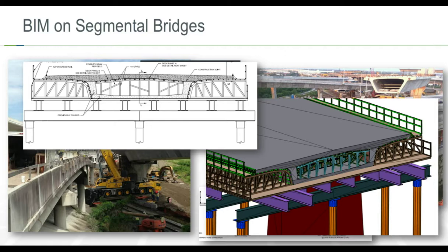We'll also use it for things just as simple as a simple sketch to show a concept, or for, in this case here, some very simple, seemingly straightforward bridge closure forms, which when the bridge is flat and not curved, everything works out really well, but when you have varying geometry, having models that allow you to coordinate all of your temporary works with that is really important. In the case here, this was a cast-in-place false work of a relatively straight portion of a bridge, but through the use of the model, we were actually able to generate quantities and, again, verify a lot of geometry that we wouldn't have been able to otherwise.